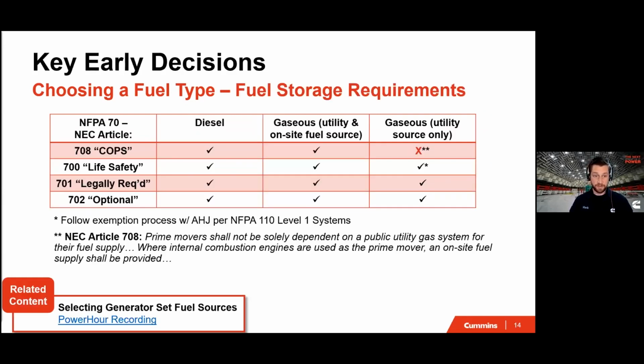And if I may reinforce one other point about diesel and gaseous fuel generator sets, there is usually consternation in and around the applicability of solely relying on the utility gas feed for life safety loads. With an on-site source of fuel with automatic changeover, with propane for example, a gaseous generator set can check all the same boxes as a diesel generator set in the eyes of the varying articles of the NEC, while still being more convenient than diesel due to the near infinite life of propane.